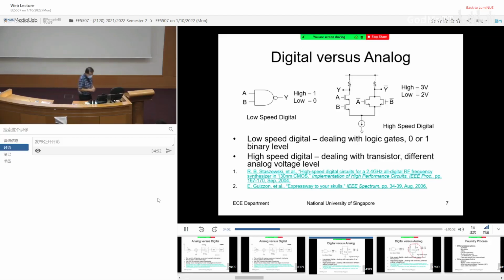Maybe I have to design the digital cell like this. Okay, this doesn't look like a digital cell, but it's actually a digital cell, current mode logic. How can it run faster? If you think carefully, digital logic runs from 0 to VDD. VDD is 1, 0 is ground. But current mode logic tries to shorten the level. So let's say the current logic only switches between 0.8 VDD and VDD. 0.8 VDD is low, VDD is high.